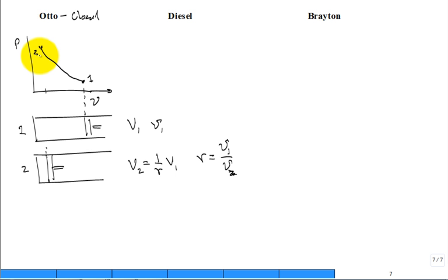Was there heat transfer? Was there any heat? No, it's adiabatic compression, and it's reversible, hence it's isentropic compression. Then why did the temperature go up? There must have been a heat transfer. No, that's what you learned in this class. You can have temperature change without heat transfer. And you can have a lot of heat transfer sometimes with no temperature change. So anyway, it comes from all that compression work.